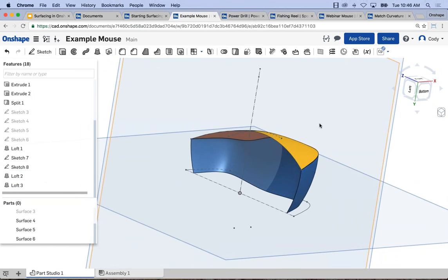Questions. What was the purpose of the symmetry constraint? I want to make sure that the radius is equal on both sides and that the endpoints reflect that. You can do that a different way. I could have dimensioned it, for example, and accomplished a very similar thing. The big thing is I wanted to make sure that I had a tangent transition between them and that the transition between arcs was equal on both sides.